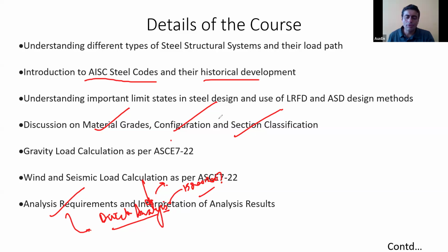So IS 800 also has this concept of notional loads, but that portion is not very well covered in the code. If you refer to section 4.3 point something, there is this concept of notional loads given in IS 800 2007 also. But it's not very well explained. And as a user, we are not able to understand what actually to do. But if you read the direct analysis method given in AISC 360, it's quite comprehensive and informative.